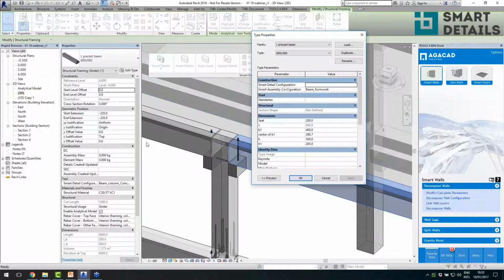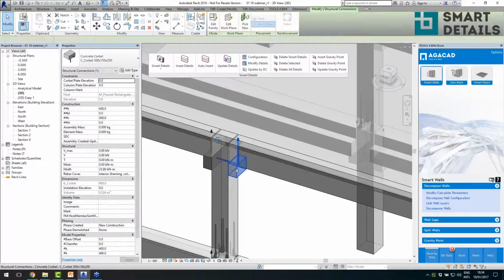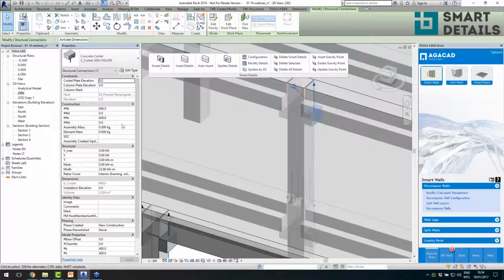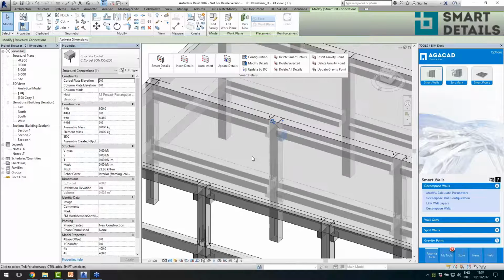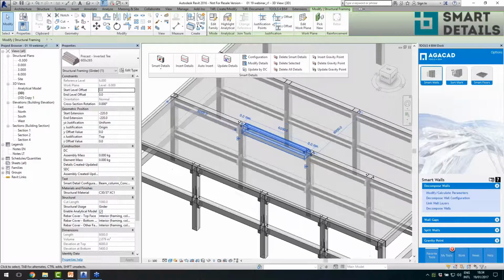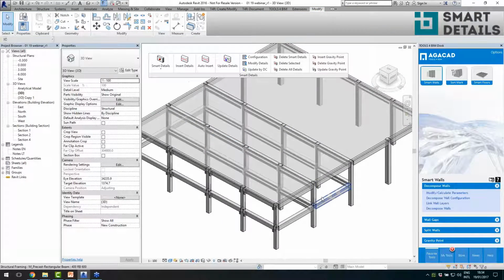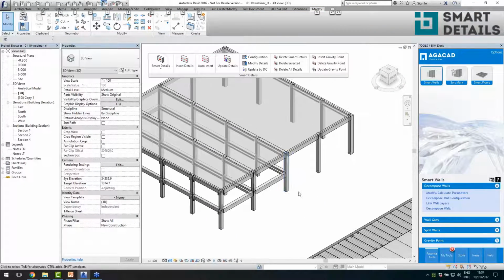So my beam has this H value of 500, so I moved this element by 500 by using this parameter. And in this case, now I have 600. So it adapts to the sizes of connecting elements, right? So it's much easier for me to create something.